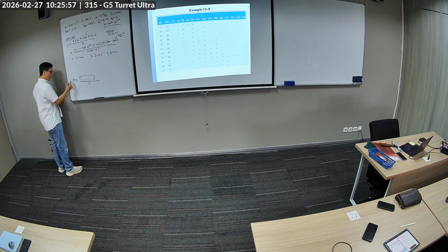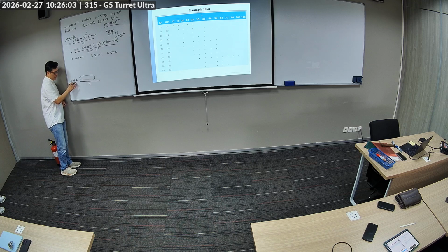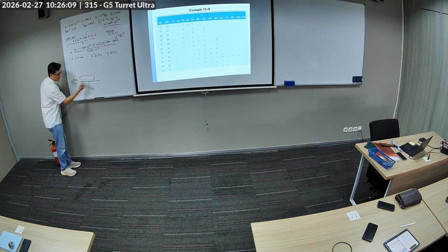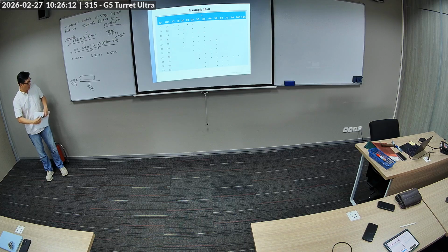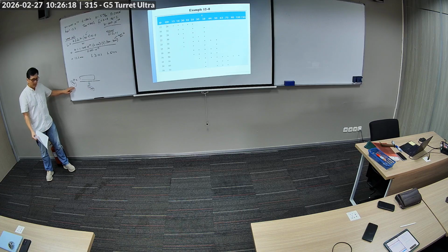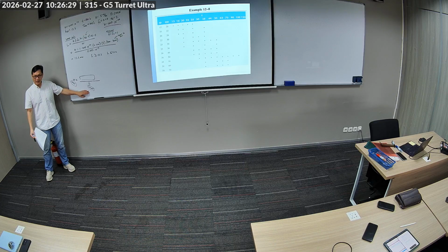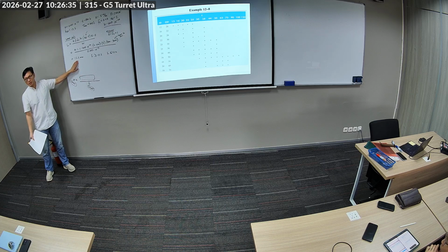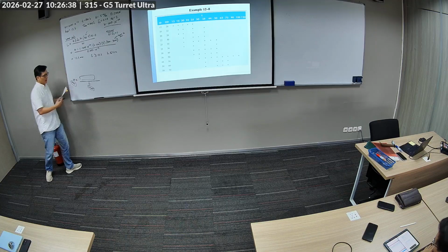Okay, so this is the wear. My wear and length of the bushing are related in this manner. So bigger L means smaller wear. Do I want smaller wear or bigger wear? Smaller wear. So you want L to be big. And so you want L to be bigger than 12.2. Does that make sense? Okay.